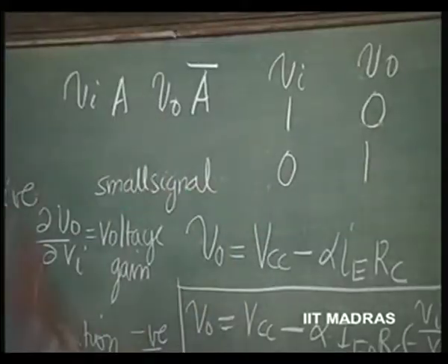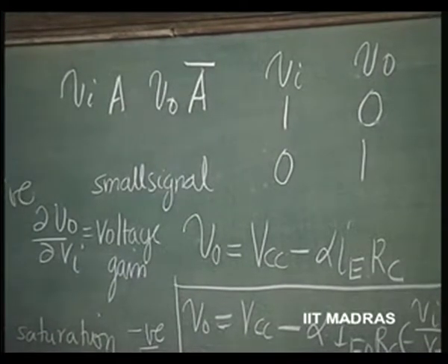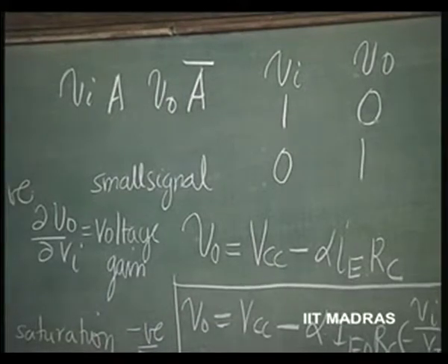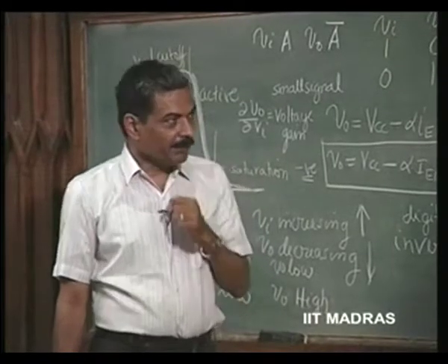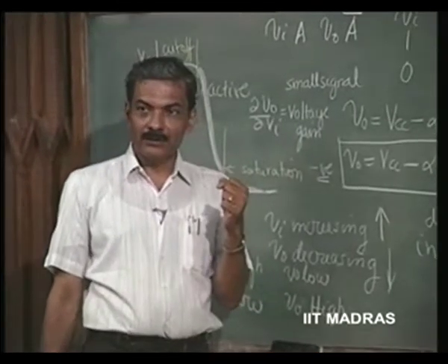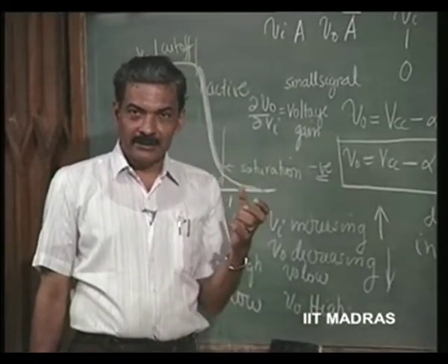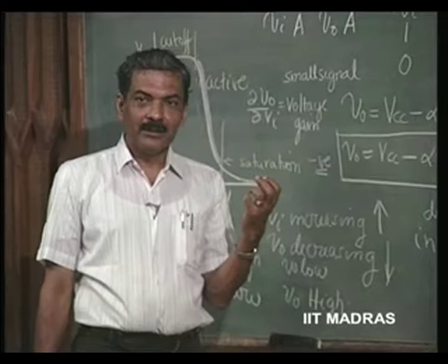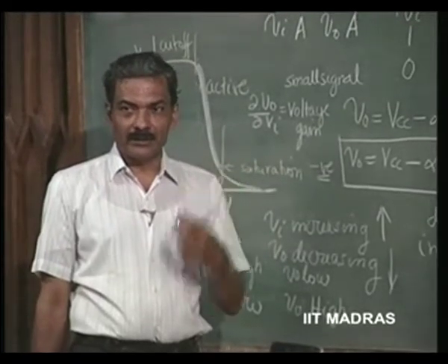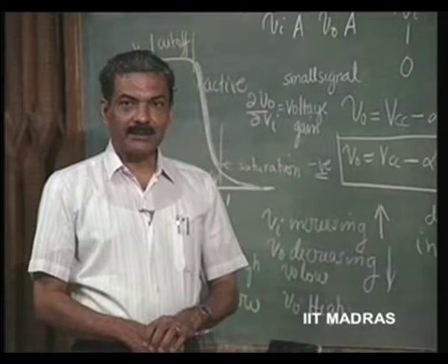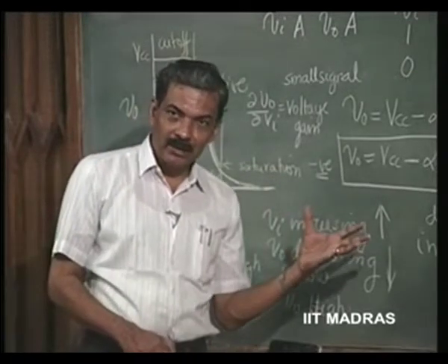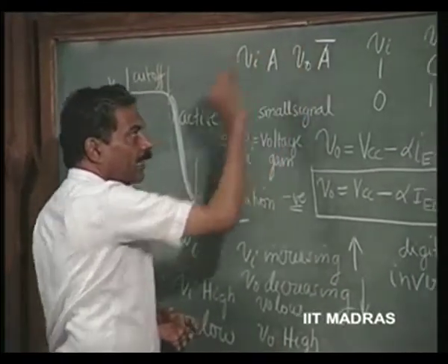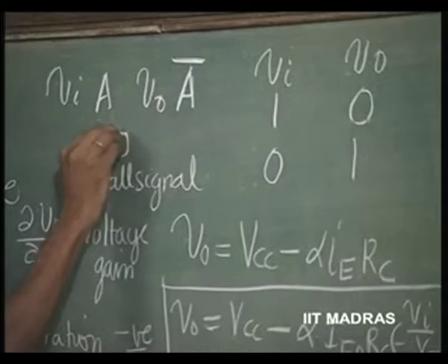This is an important basic building block of digital systems. Without this, no digital system can be fully designed. Okay? That means what we have learnt with diodes, the diode gate, we discussed AND gate and OR gate. By using just diodes, we can build AND gate and OR gate. This is the logic we had seen when we discussed applications of diode. Now adding this operation, A is input, A bar is the output. This is a NOT operation.